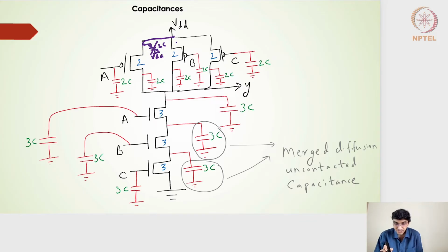As the input changes, the output should change. But this non-switching capacitance on each of these transistors on the PMOS side, and on the NMOS side, we will have a C transistor which will have one non-switching capacitance here. On both sides it is ground, so we will not incorporate this in our design, because that will not have any effect on our calculation of the delay, because on both terminals we have the DC source. So that is something I have not accommodated in this particular diagram.